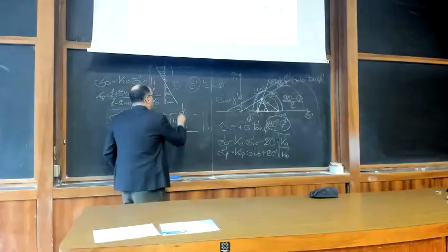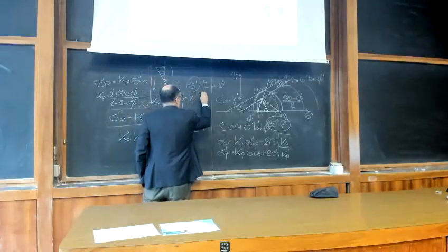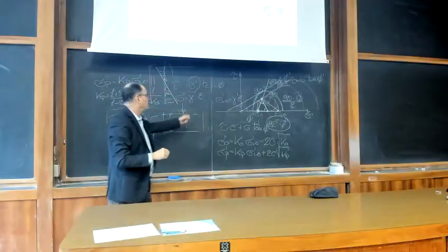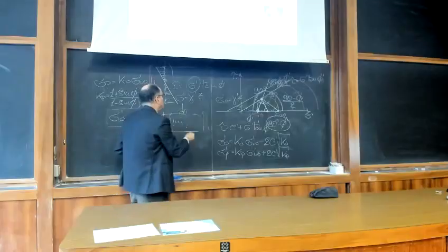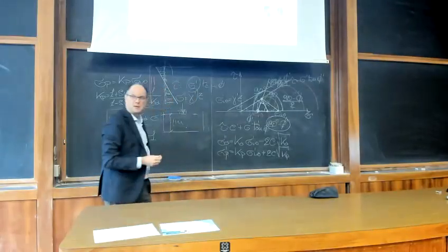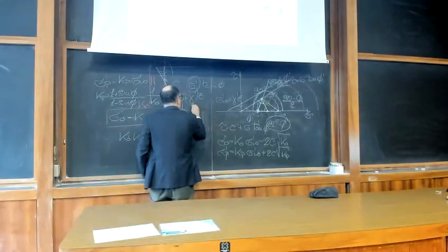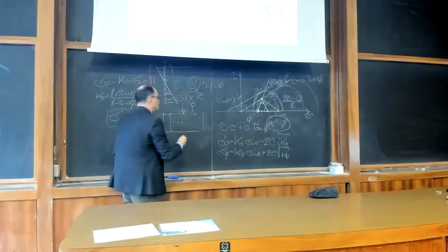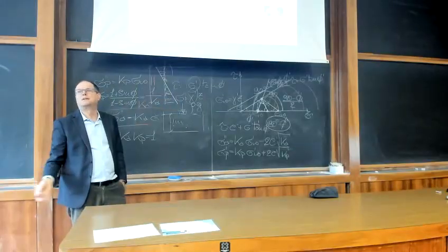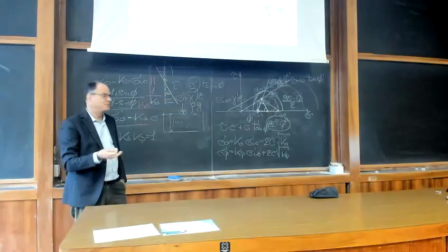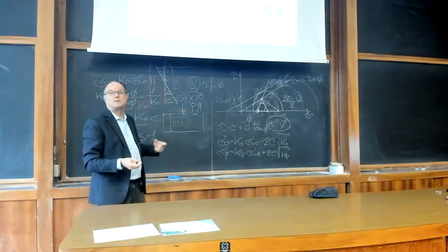And the stress, we know, increases linearly with depth. So you have gamma dash times z. Now, if you cannot increase z because you are limited in the size of your model, you can increase gamma. How can you increase gamma? Because gamma is the density of the soil, rho, times g, which is the gravitational acceleration under typical circumstances, 9.81 meters per square second. This is our gravitational field.